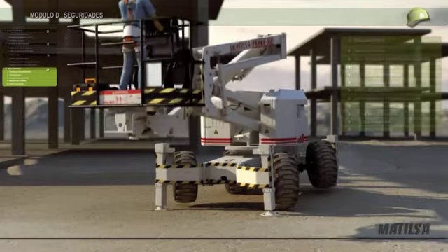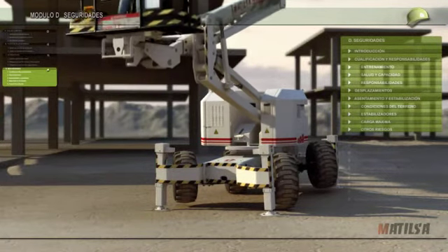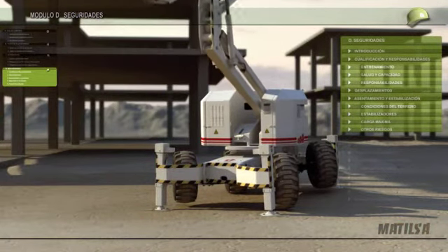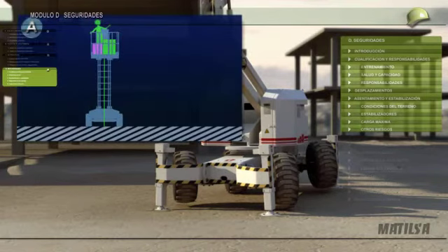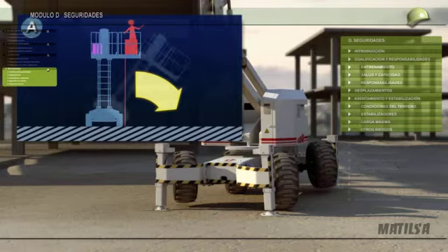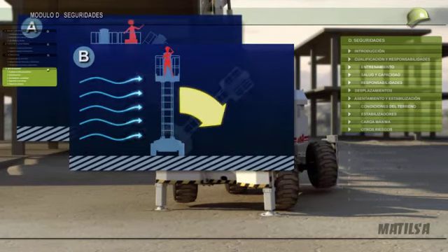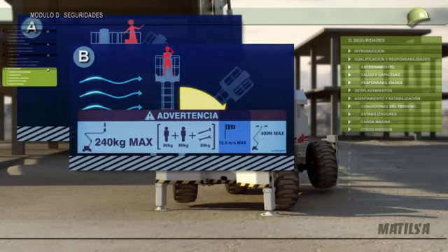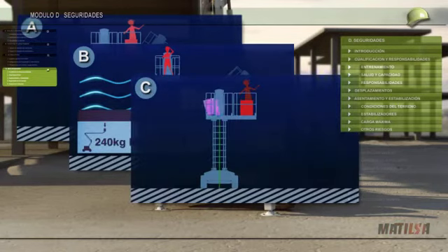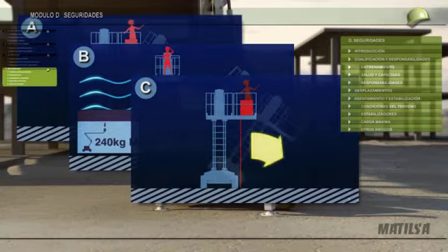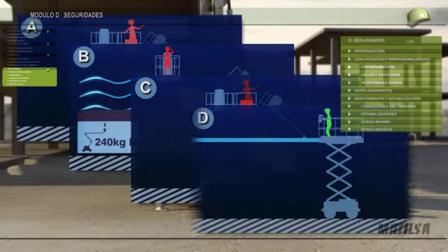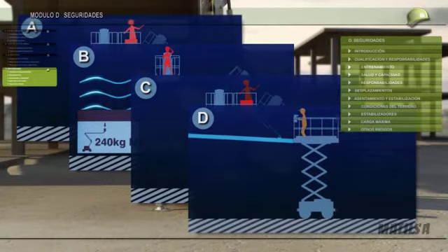There are other factors that may reduce the stability of the platform and cause overturning. Unequal distribution of the weight over the basket, especially on the scissors type ones, due to the sideways moving devices. The use of the platform in strong winds. The maximum speed of the wind will be indicated by the manufacturer. Unexpected impacts on the load due to falling objects. Pushing against another structure may cause lack of stability.